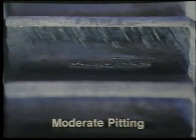The pitting is concentrated at the pitch line, which changes the involute form. Although the teeth have not been significantly weakened, noise can be generated because the involute form no longer falls within the tolerance band discussed earlier. This gear should be replaced because noise and fatigue fractures may occur.